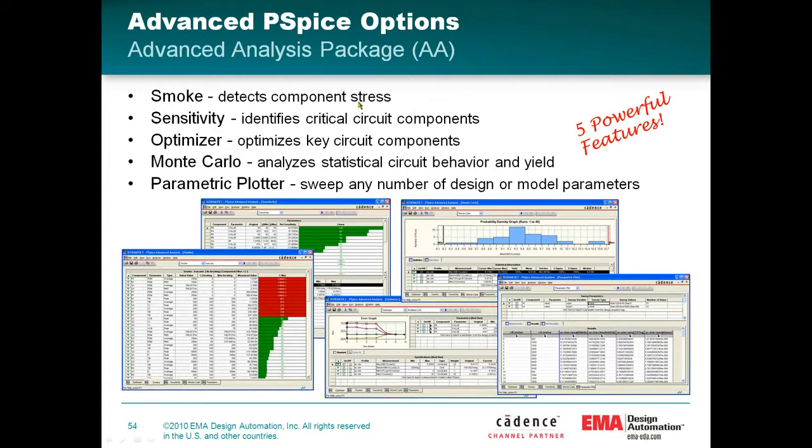Smoke is the first one I'll show you here. It basically detects component stress. How hard am I driving these? Am I pushing, for instance, a VCE on a transistor? Am I pushing that voltage too hard, or is it too close to its maximum settings? There's a sensitivity tool that basically gives you an idea of which circuits affect your component parameterization the most, and